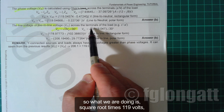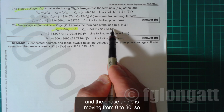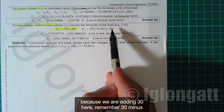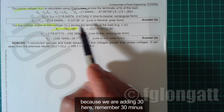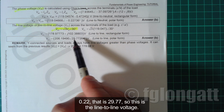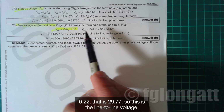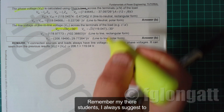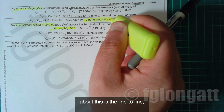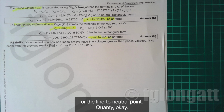So what we are doing is square root 3 times 119 volts, and the phase angle is moving from 0 to 30. Because we are adding 30 here, remember 30 minus 0.22, that is 29.77. So this is the line-to-line voltage. Remember, my dear students, I always suggest to include the remark about whether this is the line-to-line or the line-to-neutral quantity, okay?